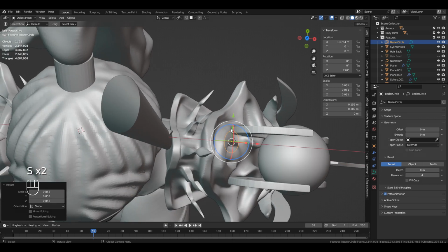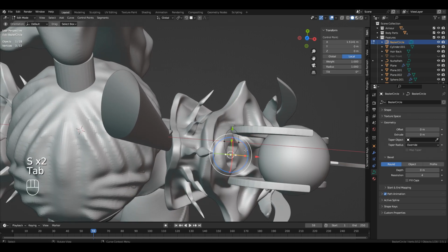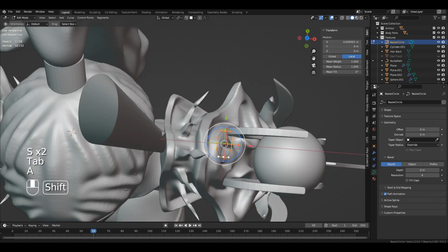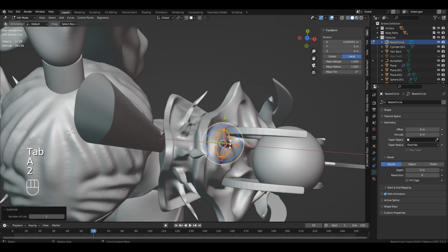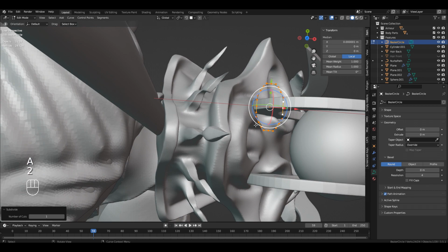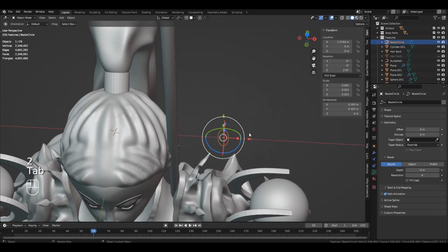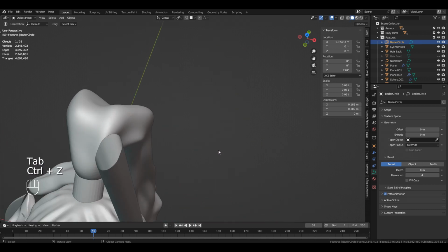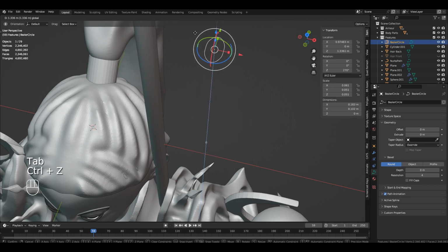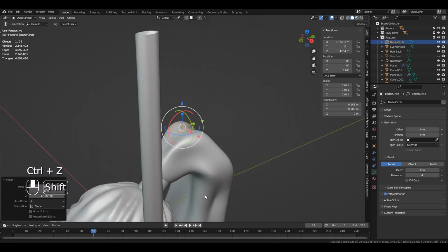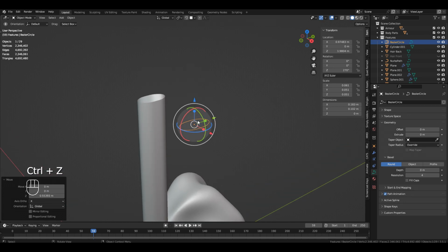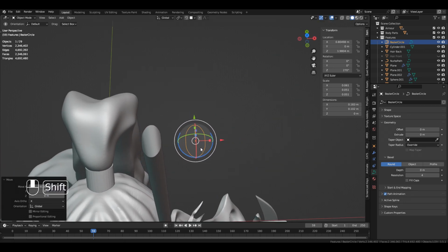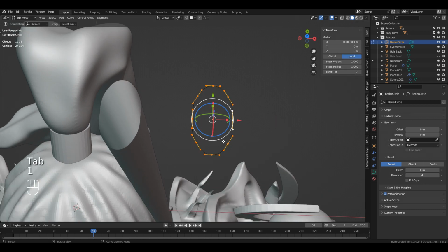Without further ado, this is how you can manipulate this curve circle, scale it up, and you can change the little handles as well on these when in edit mode. So we're going to subdivide, so that's selecting them all by pressing A and then right click and then subdivide. And then I'm just going to position this in a better position. Oops, I just moved it on the y-axis. I meant to do it on the z-axis. Okay, just bring that up. And we'll go back into edit mode, put that next to the object so you can see it take the transform.